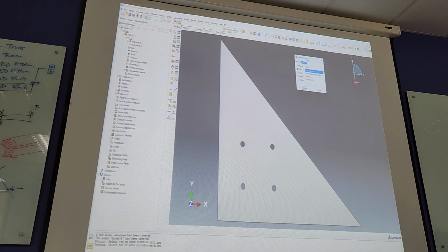Okay, now, when you go with this section, it is a solid, although it's two-dimensional, it's still solid. Homogeneous means it's got the same properties in all directions, so in X direction, Y direction, and so on. What material may not have the same properties in all directions? Composites, depending on the fiber. Timber as well, depending on the grain and so on. So you'll use a different modeling approach.